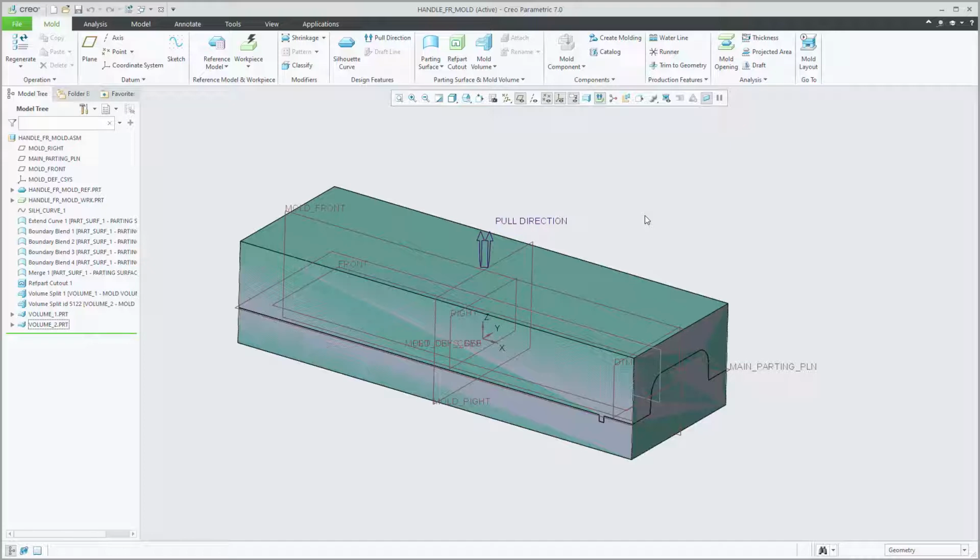And you can add this geometry to the mold and then essentially take a dummy molding of the as-molded shape. So that's what we're going to do. We're going to add a runner to the mold to deliver the plastic, and we're also going to put some features into our mold which are air vents.